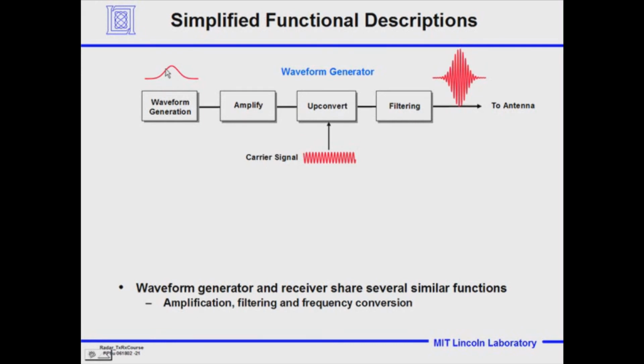microwave, where it's easy to make a very non-lossy, just exact, waveform with just the right characteristics of stability. We generate that at low frequency, and then we amplify it, and then we upconvert it to the frequency that's of interest to us. And I'm going to talk in a minute about what I mean by upconvert. When you say upconvert, I want you to think we shift the frequency, but I'm going to show you how we do that in a minute.